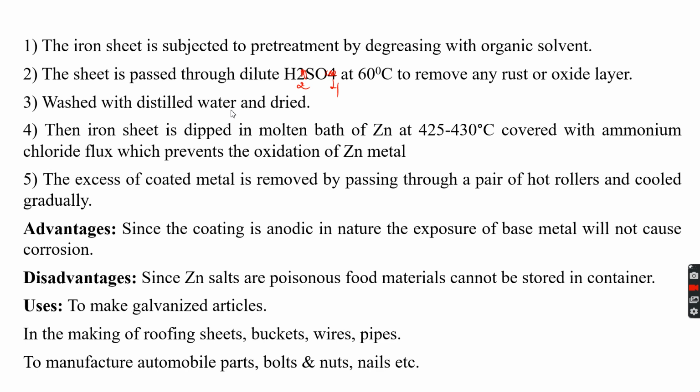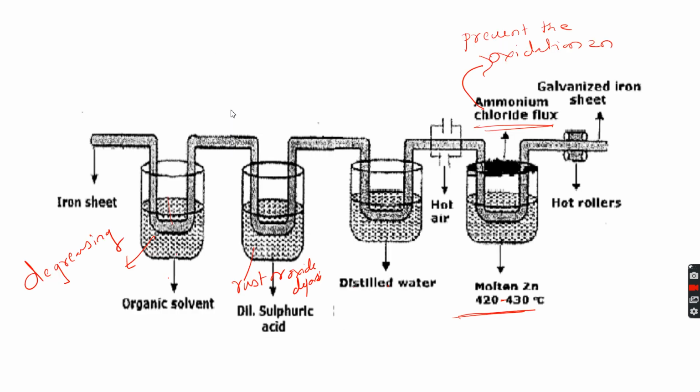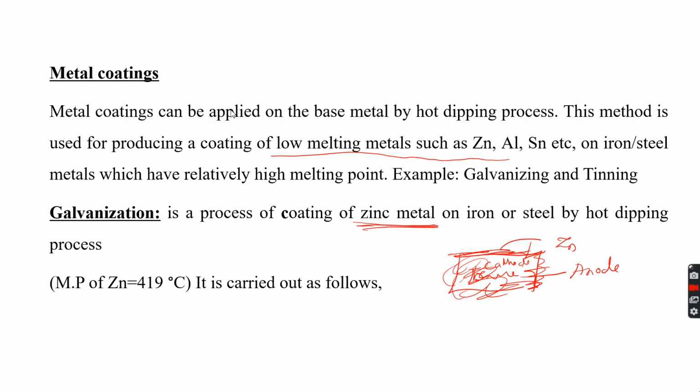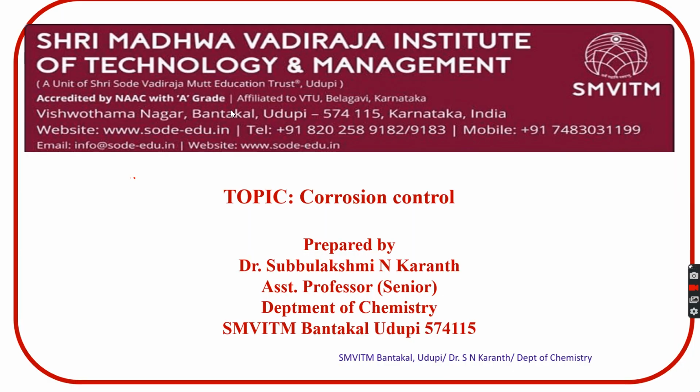Along with this, we observe two more kinds of corrosion controlling methods. The first is the use of corrosion inhibitors. While manufacturing the metals or carrying out metal finishing techniques, we may improve the corrosion resistance by introducing a corrosion inhibitor that inhibits the rate of the corrosion reaction. That may be an anodic inhibitor, by whose addition we reduce the anodic reaction, or a cathodic inhibitor introduced to the atmosphere, which reduces the cathodic reaction.